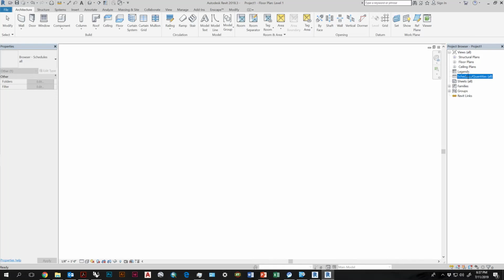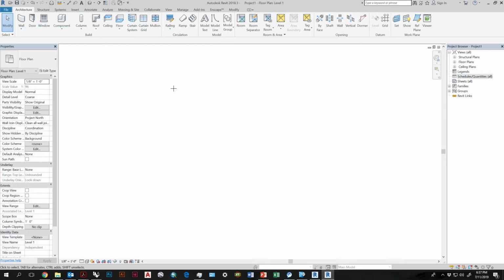You'll see your schedules, sheets, families that you have imported or haven't imported yet, and groups. And so all of these are, obviously, very important to pay attention to. So let's go ahead and start creating views and creating some geometry here, and I'll be talking about some more things as I'm doing that as well. So right now, I'm on the floor plan level 1.